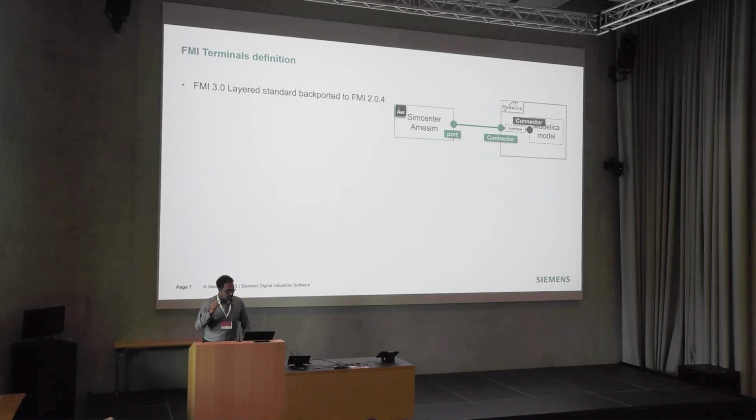To let Simcenter Amesim understand that this connector from the Modelica world is a terminal and can be translated into a physical port for Amesim, it needs to follow certain rules that we set as terminal requirements. One of the rules is writing an annotation, a tool vendor annotation, saying which type of port we have for this connector.